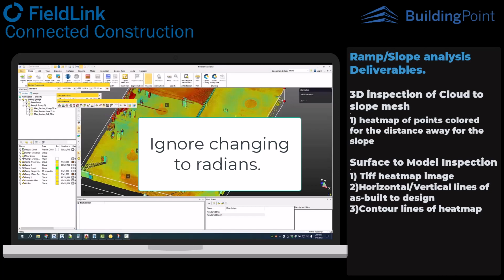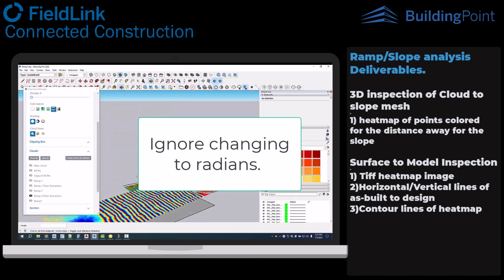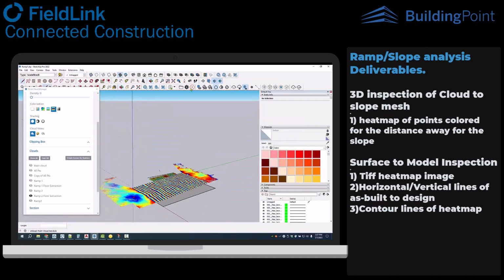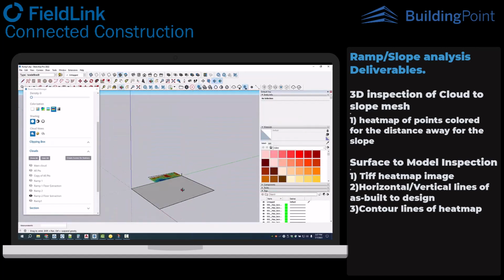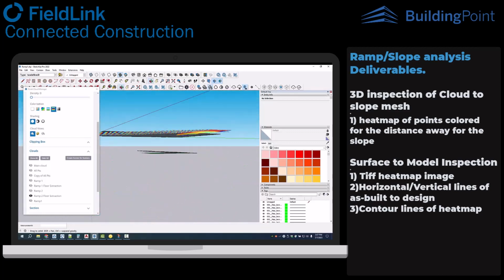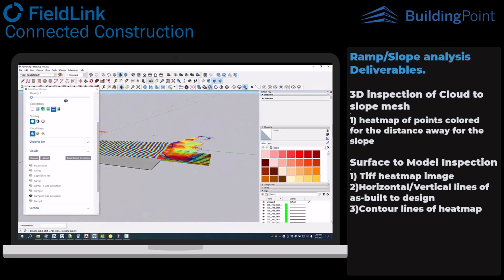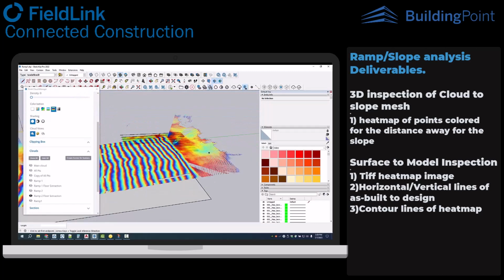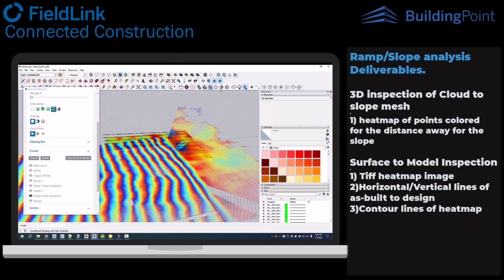So coming back to SketchUp, 2.7 is about what I have. All I do here is generally what I'll do is turn this off, create what looks like a map or a rectangle of what is going to represent the floor of this, and you can see the slope hasn't actually been created. I could create a point to this point by just hitting X and then drawing this up.